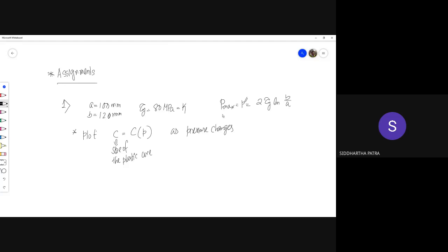You also know that P prime is the yield pressure, where plastic deformation first starts. The yielding occurs at R equals A, and that is tau y times 1 minus A squared by B squared. So as pressure changes from P prime to P double prime